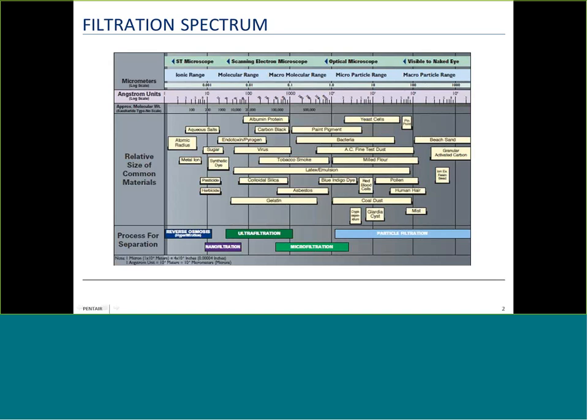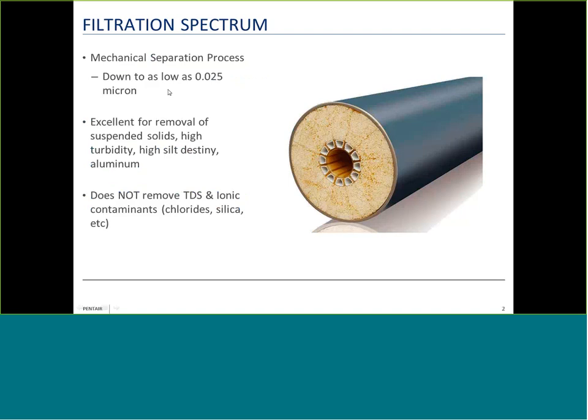Now, what the UF membrane actually looks like, these are the pores that the water has to go through that will strain out most of the molecules. This is a cross-section of one of the tubes that the water flows down and out, and this is actually the surface in between here and the outside wall of one of these tubes. And you can see the porosity. This is what this material is made up of, and it has to penetrate and come out the core. So water comes in, pushes out and through, and is strained out through that tangle of pores and pockets.